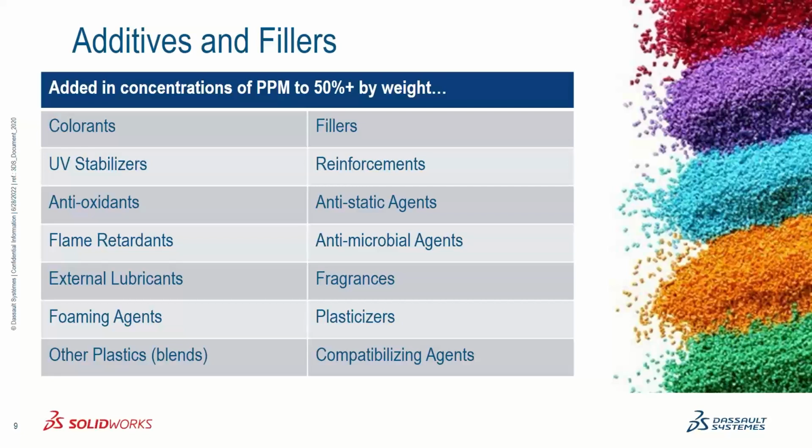These are chemical additives that inhibit or slow down degradation caused by, say, oxidation or UV exposure or exposure to heat, as well as minimizing reactions with catalysts that can break down the plastic at the molecular level. So by adding stabilizers, you can slow down the degradation of plastic due to these external factors.